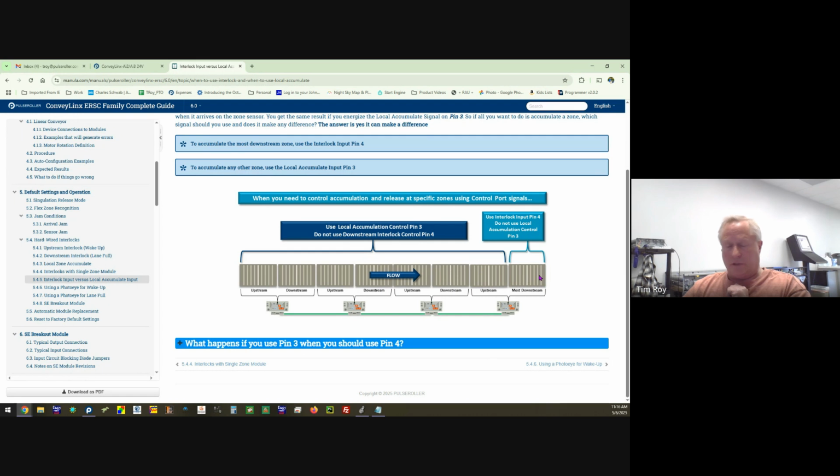The next load arrives. First, this zone's going to wait for confirmation of arrival. It's never going to get it because there's no interlock down here. Now, these are default values. The default jam time is 5 seconds. So this new load first waits 5 seconds for the confirmation. It doesn't get it. Then it waits 5 more seconds to automatically clear that error. And when it does, this load releases. The next load arrives. Well, it has to wait 10 seconds and then it can release.